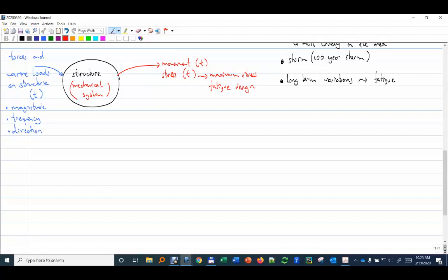So the point here is that each structure, depending on its characteristics, will have what we call a natural frequency. And the characteristics we are talking about, if any of you took any course in mechanical engineering, we can model all of these systems usually with a spring, and we can put a dampener, and we can put a mass. So this is, in a way, the inertia, the mass. We have the flexibility, which is the spring constant, and then we have the dampening.